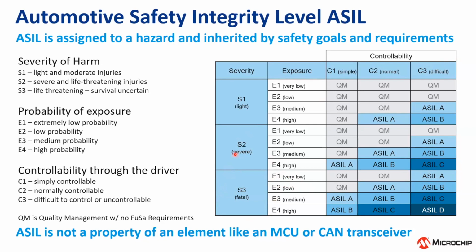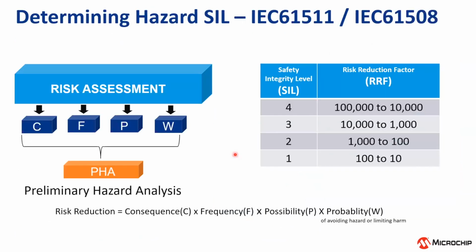I mentioned I sit in Detroit, Michigan, so my presentation is automotive heavy. However, I did want to mention that the SIL level from IEC 61508 is very similar. So in IEC 61508 or IEC 61511, which is industrial processing, we have a very similar sort of formula where we get the safety integrity level from. Slightly different terminology, but overall, we have a similar way that we get the safety integrity level.